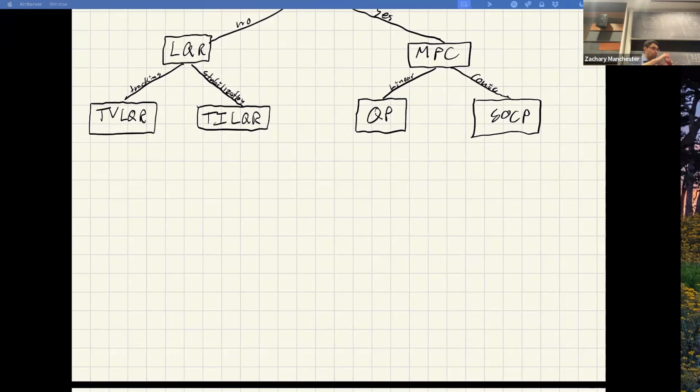And then what you can do is roll that out with the LQR feedback. A single linearization, a single K won't work, but a time varying set of Ks will basically stabilize a tube around that trajectory. And that works extremely well. So that's the classical combo, actually. For a long time, the recipe for doing these crazy things was: offline, you do nonlinear trajectory optimization. You get a reference trajectory that might do the crazy thing. And then you linearize around that and write down an LQR tracking controller or a convex MPC tracking controller that's time varying. And that basically will stabilize you within some tube around the nominal trajectory.